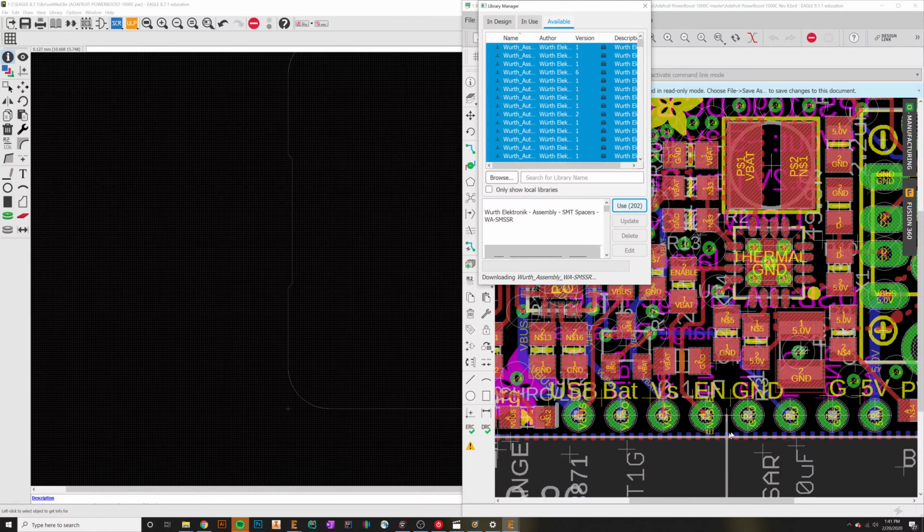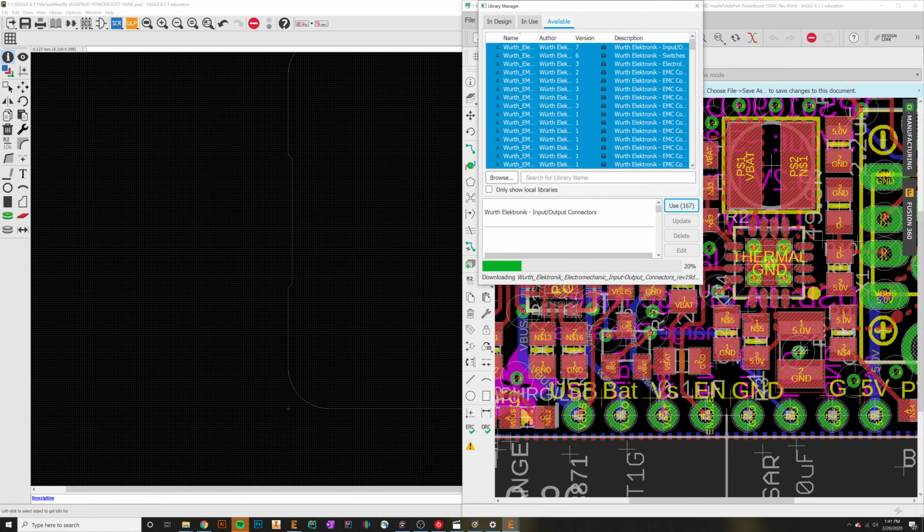Okay, meanwhile, while this is going on, one thing I want to say is that one thing that's preventing us from being able to simply copy everything in here and paste it over here is what we had mentioned before: in a library, a device is made up of a package, which is the part we're designing, and a symbol. So whenever we do a copy of all of these elements in here, each one of these elements is a device in itself. If I try to add a device to a package, it's kind of a contradiction because inside of a regular device, I have a package. So a device cannot exist inside of a package. So when I try to copy it, I would get an error.